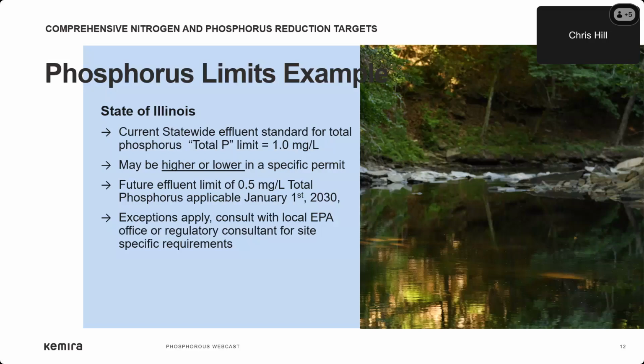In an NPDES permit, the limit will be expressed as a total maximum daily load, often in pounds per day, as the TMDL. To determine the allowed concentration, you would need to know the flow of water in gallons and multiply this by the concentration in pounds per gallon of phosphorus, and thus limit the flow, concentration of phosphorus, or both to stay under the allowed TMDL. My colleagues will now explain methods to control phosphorus.